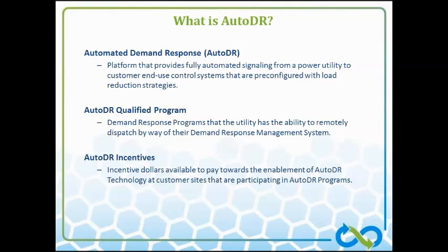We can talk through different ways to curtail load to participate in demand response. But with that said, AutoDR, or automated demand response, is essentially a platform that provides fully automated signaling from the utility to an end customer in order to shed load for demand response events.